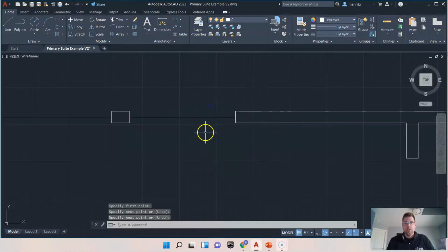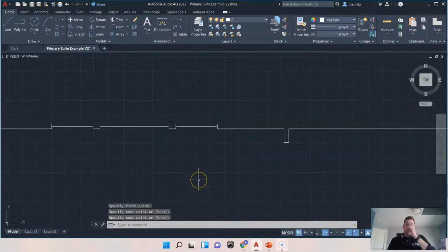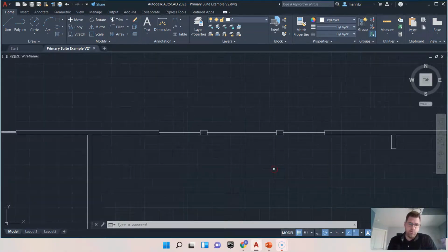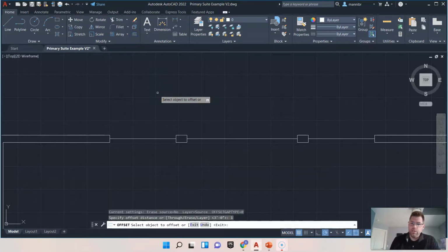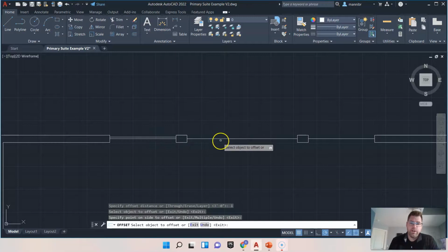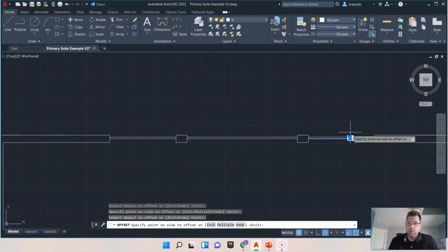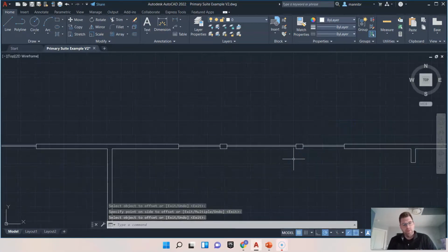Snap to the middle there. So I have to add a thickness to it. Everything is cut from 4 feet off the ground, and so windows have a thickness to them. Generally, we're just going to go with 1 inch. So I have to run my offset to 1 inch, and then I just click on my line and run it out on the outside, and that represents my window pane. And we can change those colors later.